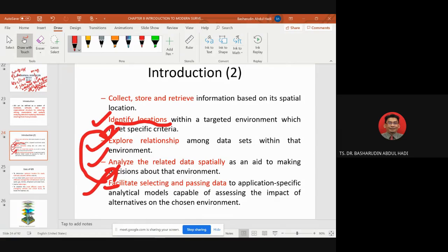If you want a housing development, of course you don't want your housing to be flooded, or a flash flood and so on. So don't select a piece of land that is flooded every year. You can use GPS to visit the place, log the data, and then go to Google search by coordinate. You can get to the point.